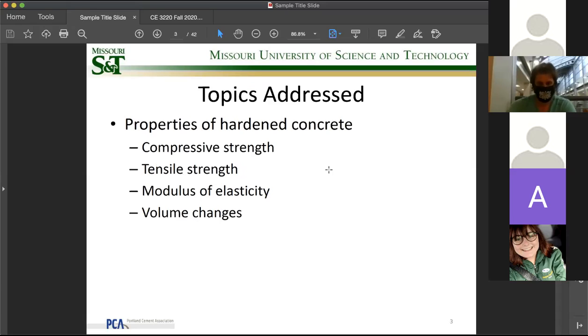First of all, concrete. So we know concrete has a wet or dry state, okay? Uncured and hardened state. So right now, we are mainly interested in the hardened state, okay? So for the standard or for the design purpose, these are the parameters that we're interested in. Compressive strength, how much concrete can take in terms of compression. Tensile strength, how much concrete can take in terms of tensile stress or crack. Modulus of elasticity, Young's modulus. Volume change, okay? So these are the 4 critical parameters we're going to use to evaluate the concrete.